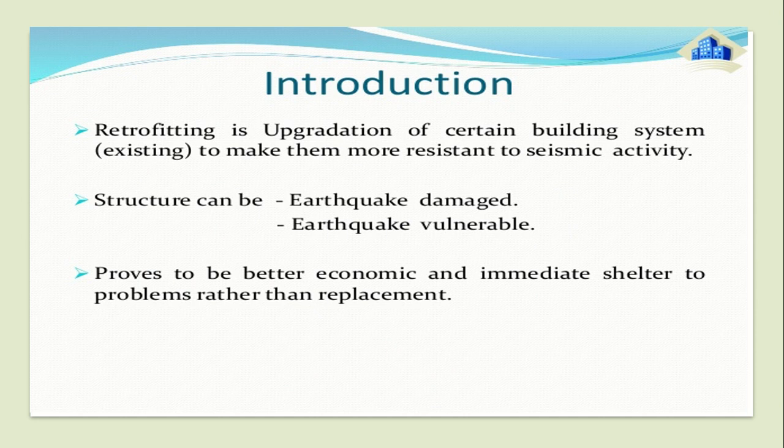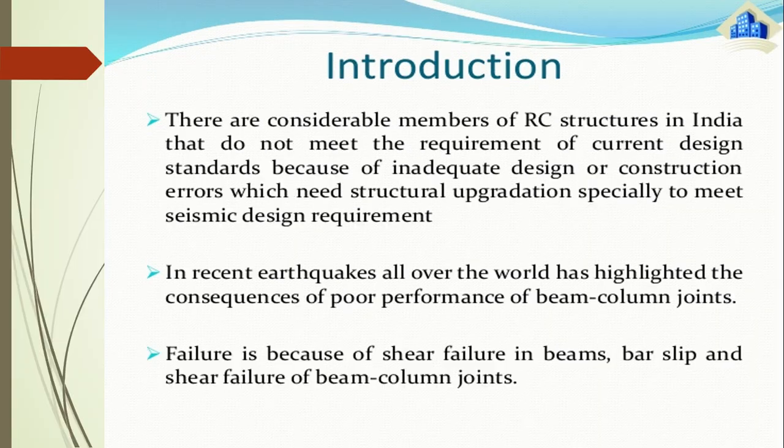So, retrofitting is the upgradation of certain building system to make them more resistant to seismic activity. This structure can be earthquake damaged or earthquake vulnerable. It proves to be a better economic and immediate shelter to the problems rather than replacement. So rather than going for a demolition of the structure, we can give strength to the structure so that it could be used for a further long period of time.